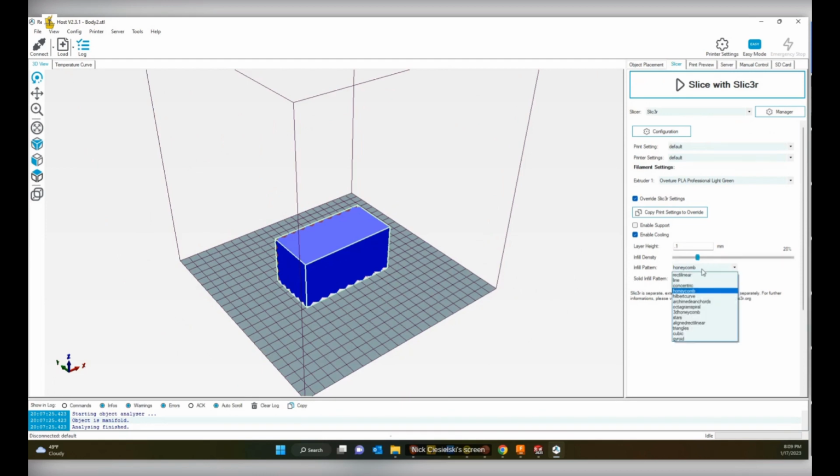And you have options for infill patterns, rectilinear, honeycomb. That would all be up to you to figure out how you wanted to do things and experiment, see what works best. If you're doing something that's supposed to hold actual weight versus be sort of decorative, you're probably going to want to print it at 100% infill. Certain things I've seen spec, especially with ABS, that you want to infill at like 105% so that it overfills, so that when it shrinks, you're back to the size you want.